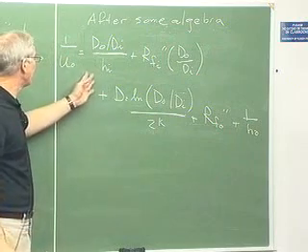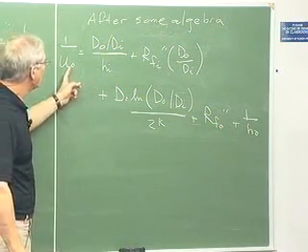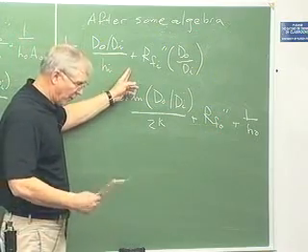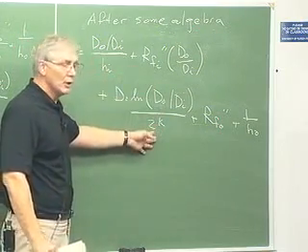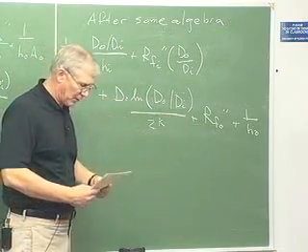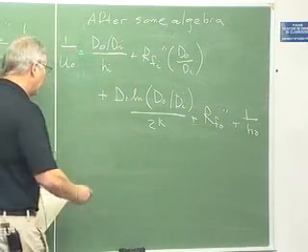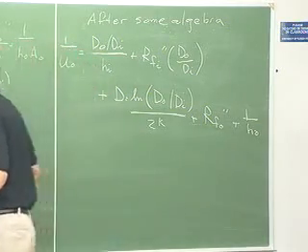Okay, now from this expression, 1 over the overall heat transfer coefficient, we can see on the right-hand side that length does not appear. So the overall heat transfer coefficient does not depend on length.